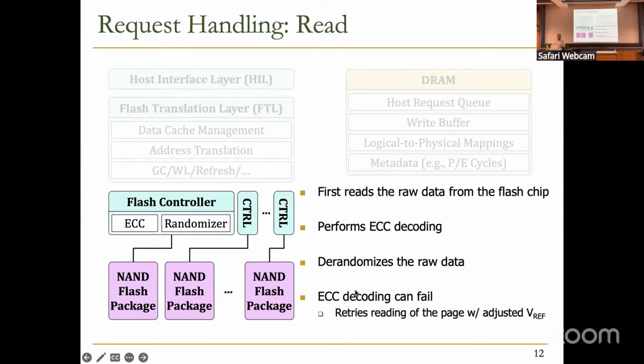The thing is that it might be the case that ECC decoding fails. When ECC decoding fails, you need to retry the read. That causes longer latency for flash SSD reads. Sometimes for one read, you need to retry it several times until you get it correctly.